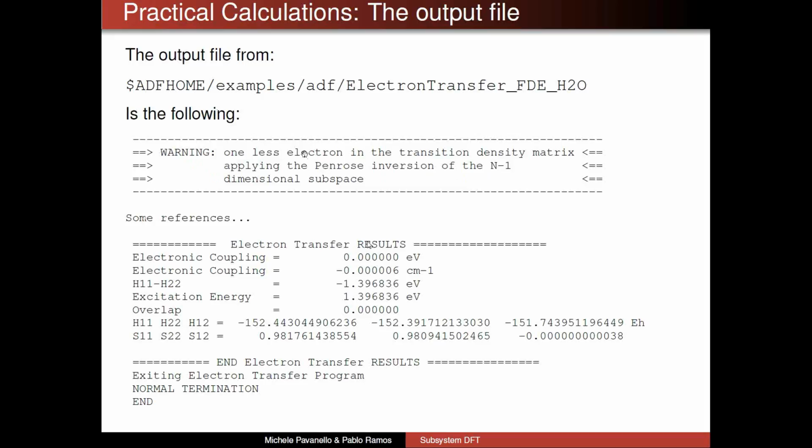Although everything is fine, if it kicks in, you're fine, it's numerically stable, you might want to check that other configurations of your system are also yielding correct couplings. You clearly see that the coupling is incorrect because you get some unphysical electronic coupling when the inverse of the transition overlap matrix is wrongly carried out. In that case, you just increase the inv threshold to say 10 to the minus 2, and everything should be fine.